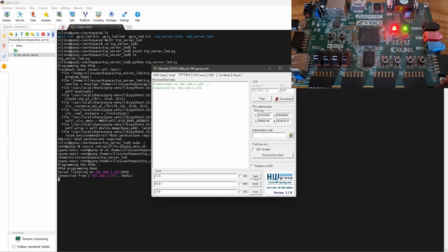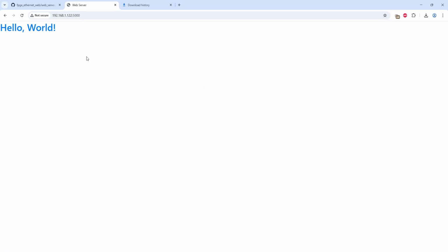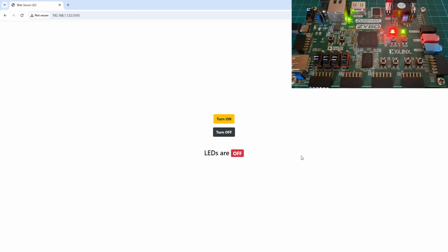In the last few videos, we learned how to turn LEDs on and off using a TCP connection on the Zynq FPGA. In the most recent video, we also learned how to create a basic Hello embedded web server on the Zynq FPGA. If you haven't watched that video, it's better to visit it first. Now, in this video, we are going to combine both of the previous tasks to create an embedded web server that controls the LEDs.